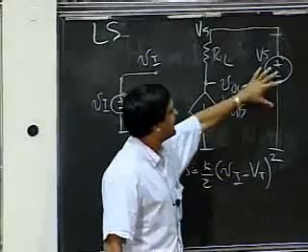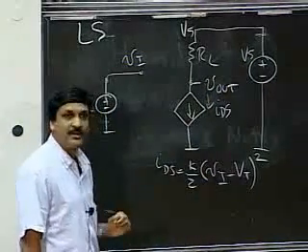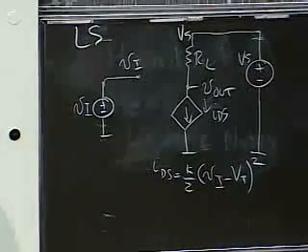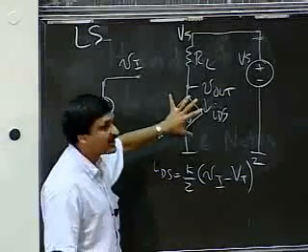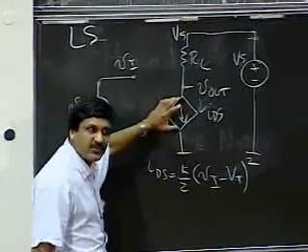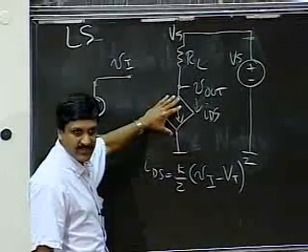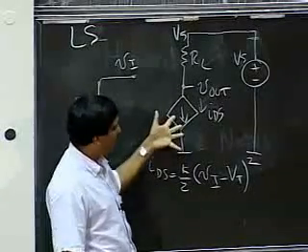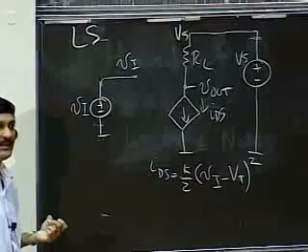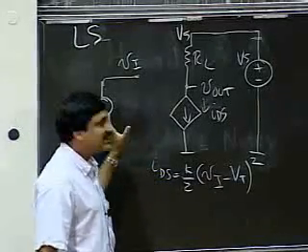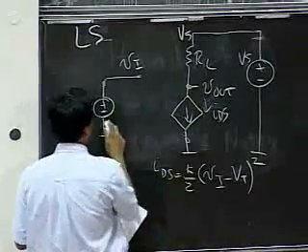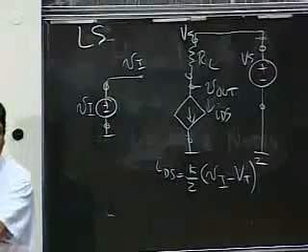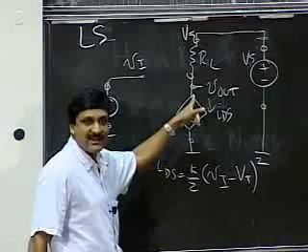In other words, here's a VS source. Here's a dependent current source. Let me replace them with their linear equivalent circuit models, in other words, with their corresponding small signal element models. And I'll show you what those are in a second. The resistor has a corresponding small signal element. The dependent current source has a corresponding small signal behavioral element model. And what I'm going to do is keep the same circuit connections, and simply pull out the large signal model for the element and replace it with a small signal element model.